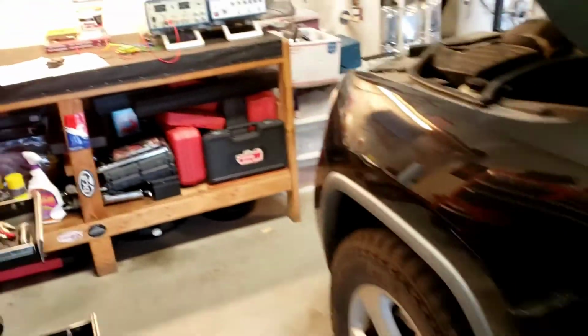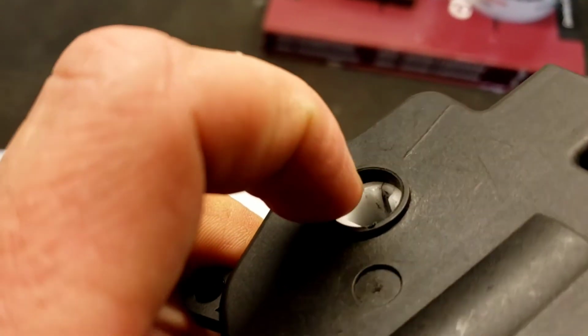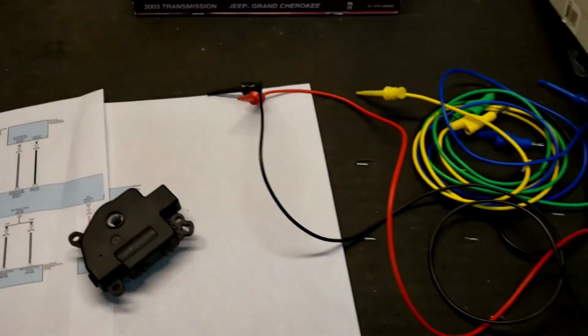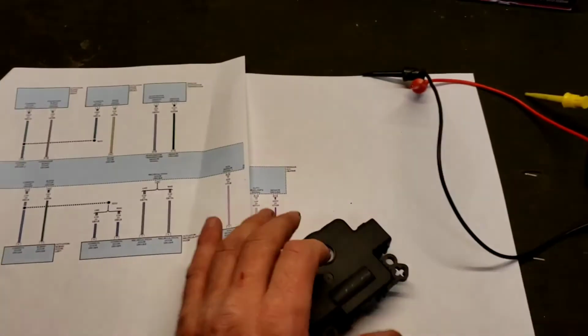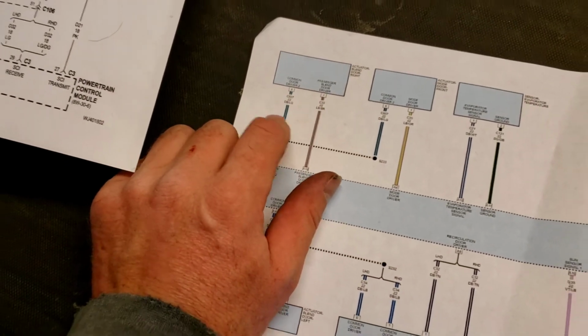We'll put all this back together. This Jeep is good to go. Again, the reason I checked the wire integrity going to it is I found 2 problems with this. One, it had a little crack right there. So it's slipping on the gear, pushing on it, because it knows it needs to have an end stop. There's only 2 wires, right? Give 5 volts, ground, 5 volts, ground, and it stops it.